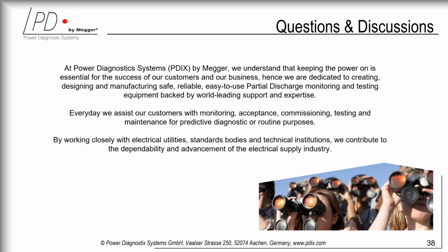Okay, gating. We have seen on one of the slides the disturbance antenna or a CT that we use to pick up external noises, noise pulse signals from ground sheets or from radiation, from corona, from overhead lines. And these pulses are brought to a separate input of the instrument. So it's a special analog circuit that is separating these pulses from the measurement pulse. So whenever such a disturbance pulse appears in the system, a so-called gate is opened on the measurement pulse and is then rejecting this disturbance pulse from the measurement pulse.